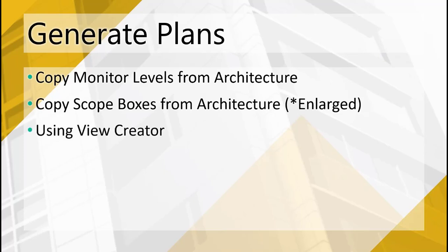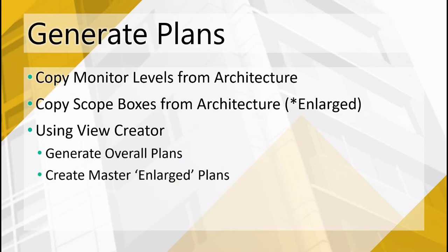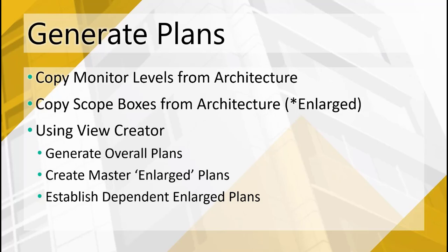Then I'm gonna be using View Creator so that I can generate all the floor plans, the main plans, the enlarged master plans, and the dependent plans for the areas A and B for all my different levels in my building. So I'm going to be doing the generate of the overall, the creating of the enlarged, the dependent views, little views right there. I'm going to generate all those floor plan views, and I'm going to do it as quickly as I possibly can.